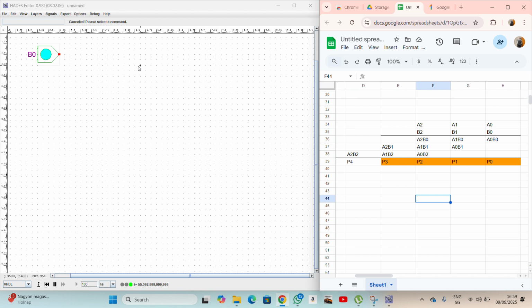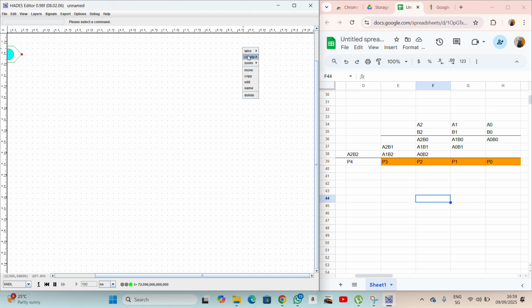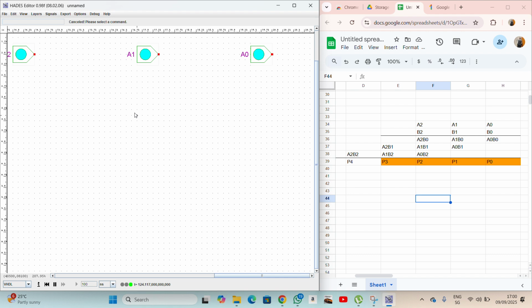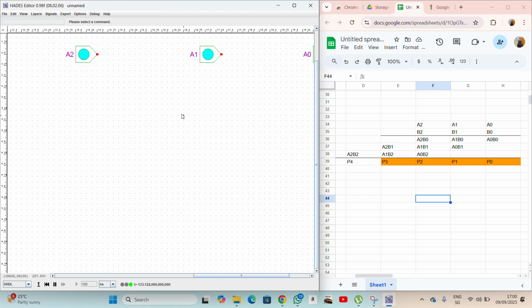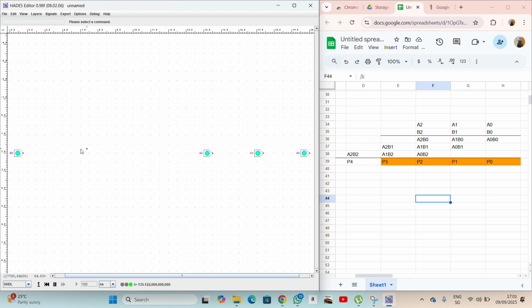Then now the next thing is to have both A2, A1, and A0 on this other side. I want to create a very big space for that because the design is going to be a very big design. So that's why on this side, I will create IO IPin switch. Then now what I need to do is to simply do the multiplication. And remember, the multiplication, we do it using the AND gate. So I can say Control plus F. Now this is what we have. So I do the multiplication by simply using the AND gates.